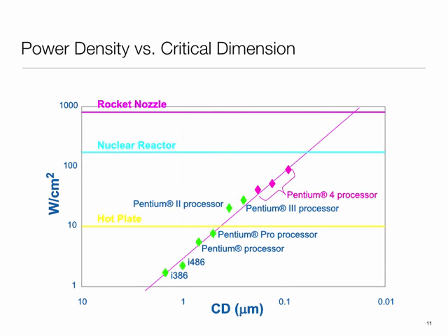This is a slide a few years old, as you can see from the feature size and all out here. But the main point I wanted to bring out is that as Moore's law kept shrinking chips, more and more transistors got packed in smaller and smaller area. And if you work out the way things scale, what that basically boiled down to is that the watt per centimeter square, which is basically how much power, so how much power you are dissipating from a unit area, keeps growing, okay?